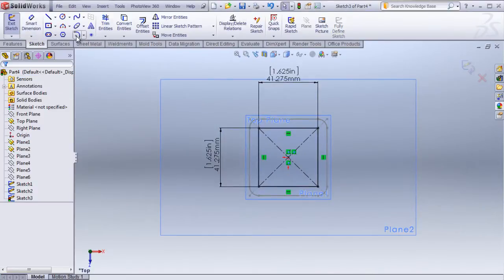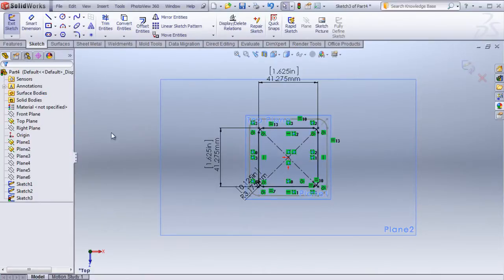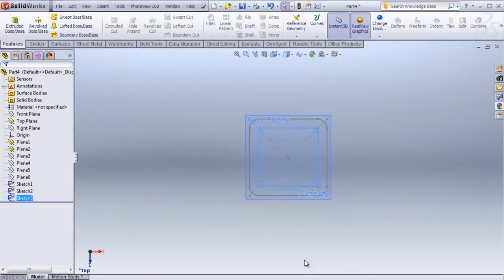Go, this is ready as well, and the fillet amount here is 0.125 inches. Got it going. I'm just going to provide a fillet real quick. All 4 points have been selected. I'm clicking OK. So now this profile is ready as well at the bottom of the plane.